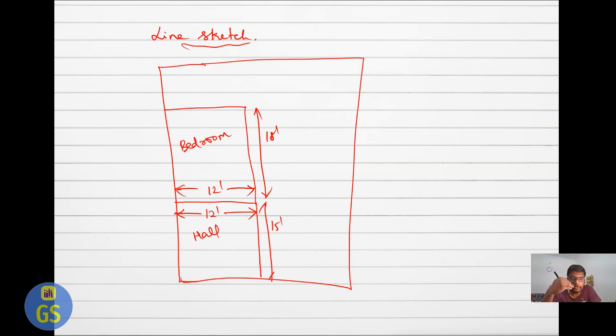So we come to know the idea of what my room size is. According to my room size, I arrange my rooms with the respective dimensions. Here I'm going to make a bathroom, so water closet. I'm going to take it as 6 feet over here, and this side as 7 feet. Like this we need to prepare a line sketch. When you develop this in AutoCAD, it will be much easier to understand.